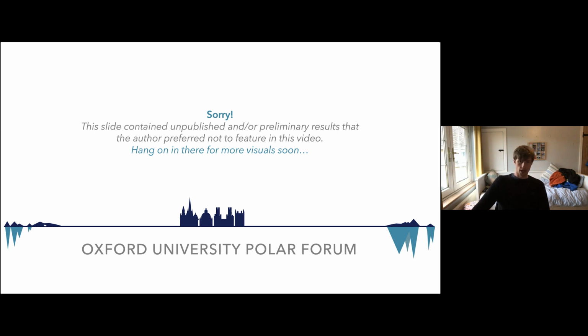And this red dashed line here is the maximum effective stress we would have if we just have ice. So if we have no water present, so no water to lift up the ice, only the weight of the ice on the bed. And we can see that all our clusters don't go above that maximum effective stress, which is a good sanity check. It's a good verification that our data is perhaps making some physical sense, in the sense that we don't predict effective stresses greater than the effective stresses that we could possibly generate in this system. But we do see effective stresses very close to this, suggesting that in some places on the bed at certain times, there is no water present.